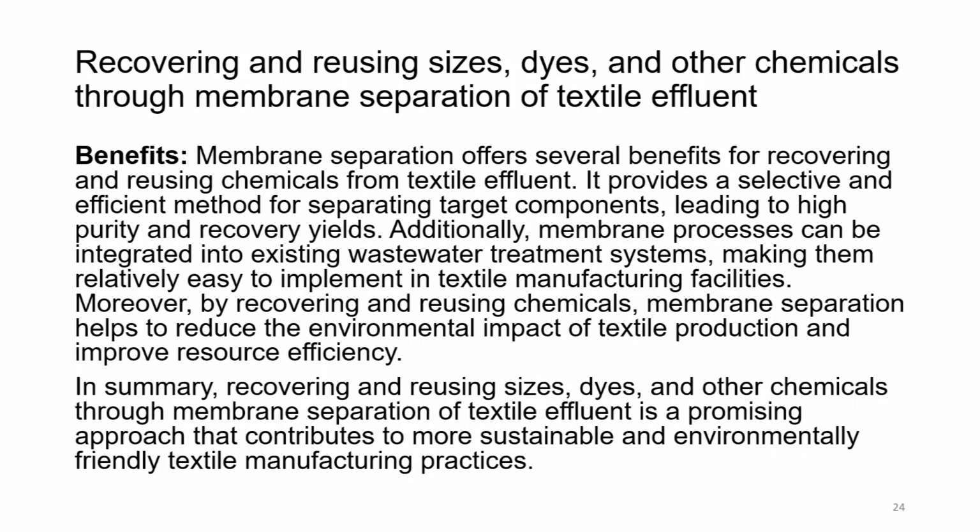Benefits. Now, let us look at the benefits from the recovery point of view. Membrane separation offers several benefits for recovery and reusing chemicals from textile effluent. It provides a selective and efficient method for separating target components, leading to high purity and recovery yields.